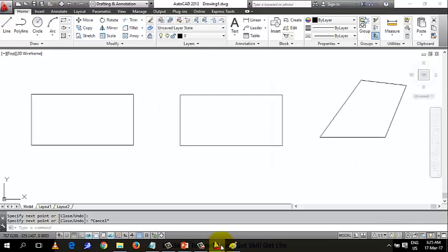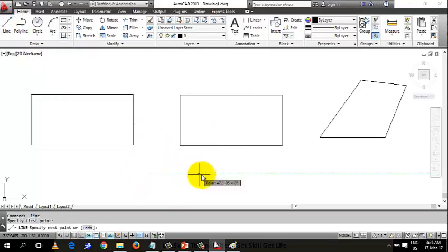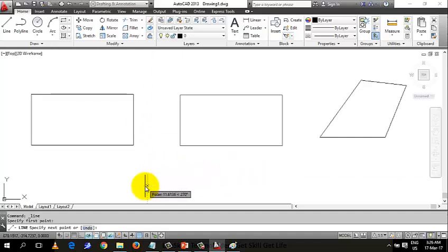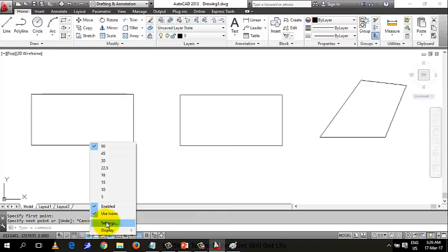So let's go back to AutoCAD. And I want to use polar tracking. But the problem is this: if I start the line command, can I get a line at angle 60? No. The best I can get is to move at angle 90. Look at that box showing. To move at angle 0, look at it there. To move at 270 and to move at 180. If I want to move at 60, I will right click this polar tracking and click on settings.